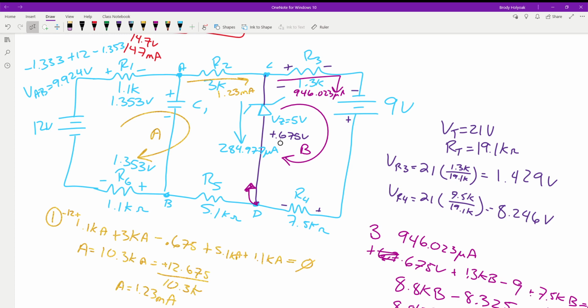Did they actually do that? You can. That's pretty sick. You can have a switching circuit in here. So what it would do is it would switch between this current coming in, and then it would switch it to where it would take it and go out. You could also use it as a relay. This could be your normally closed position, and as soon as it goes to normally open, you would throw the switch and the capacitor would be then connected to an LED. Then the capacitor would discharge, and then it would trigger back, and then your relay would open back up and have it charge. So you could use it as just an indicator. You can now have a flashing light. Obviously, this is kind of overkill for a flashing light, and there's some more stuff you'd have to add, but you could do it.